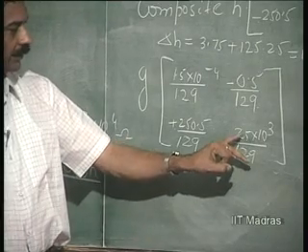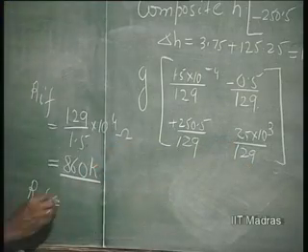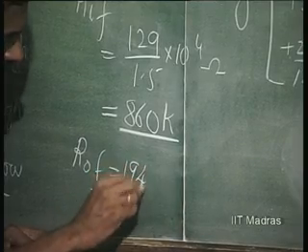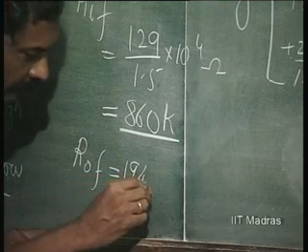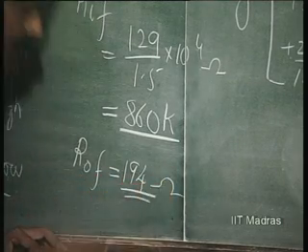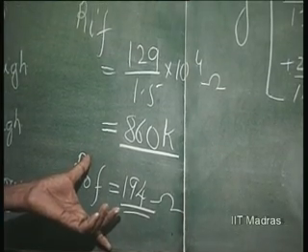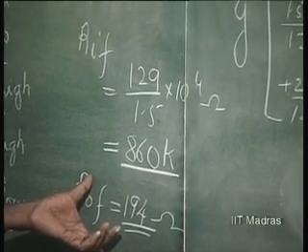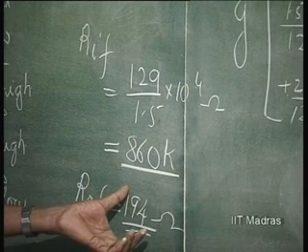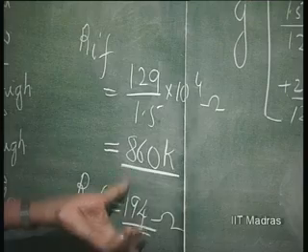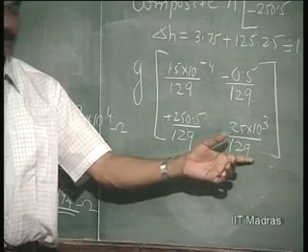So if you take it as 120, this will be 194 ohm. Is that correct? So 194 ohms. We started with an amplifier with an output impedance of 10 K, and we have now gone towards an amplifier whose impedance is only 194 ohms. See how things have improved. So these two things have drastically improved.